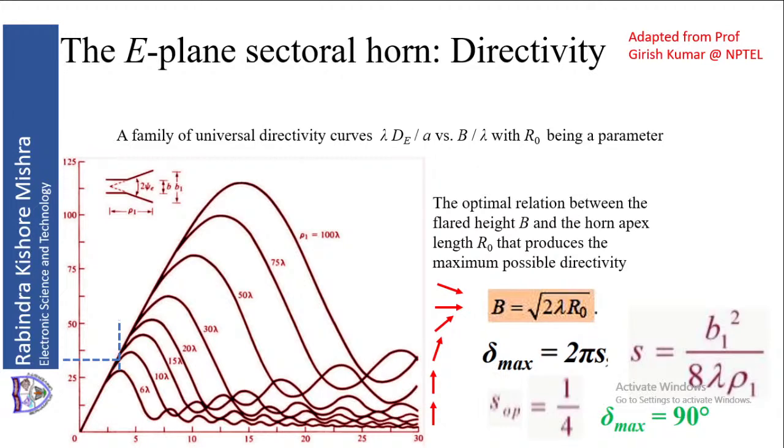When you come to 10 lambda, it will be 10 times less than that. From that, it will be half of this, about 6 lambda. So it is a small antenna. We usually require a smaller horn antenna for feed. We don't require a larger antenna, because the feeding antenna should not block the aperture of the reflector. So consider a small antenna.